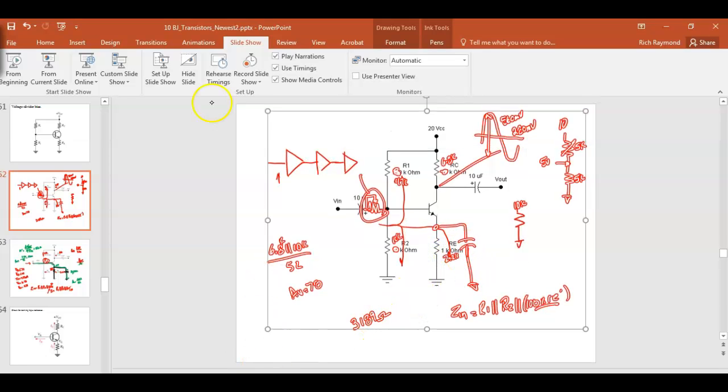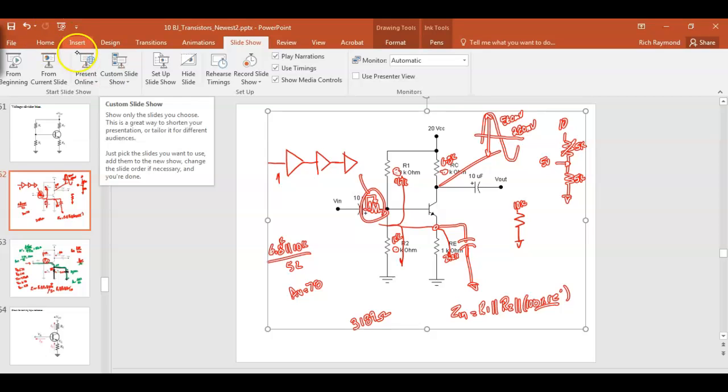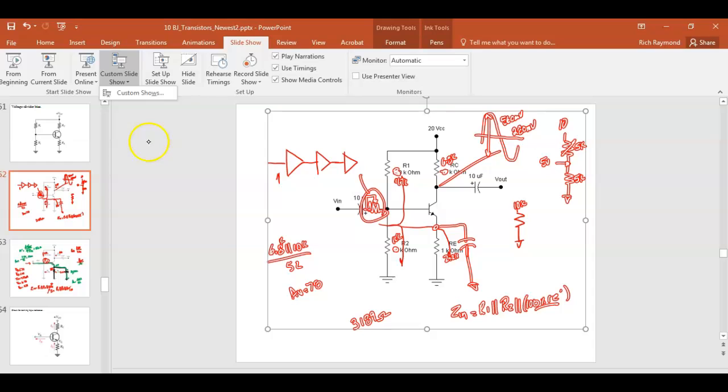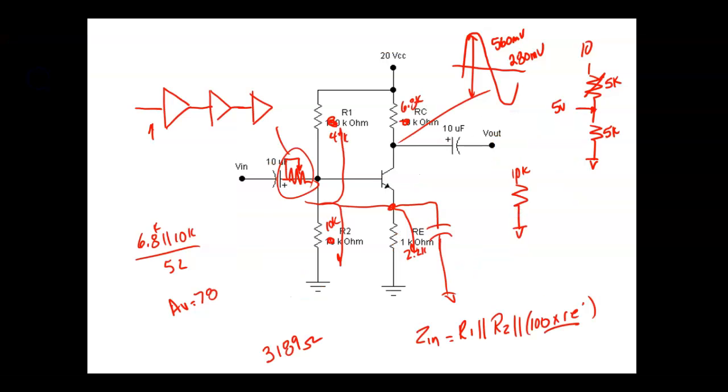I'm opening RE. Oh, sorry, wrong thing. So I'm opening RE. And I'm measuring right here. So I'm measuring 1.78 volts right there. I'm measuring 1.78 volts right here. So it means there's no current flow through that resistor, right? Because, understand what I'm saying? Yes, no.